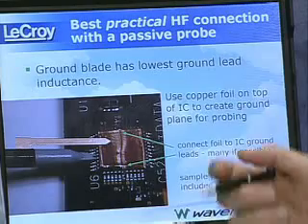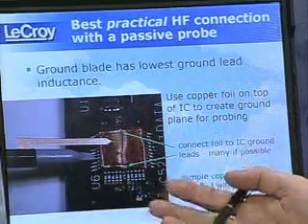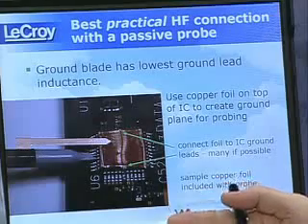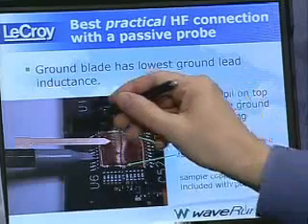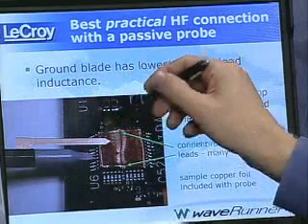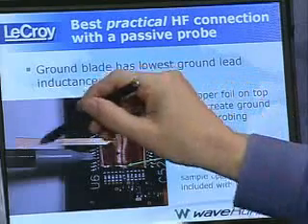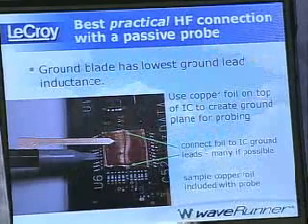Right. So people often ask what capacitance that probe is, but they often don't ask what inductance is the ground lead? And they probably should. But this blade shape of ground has much less inductance in this geometry than your usual wire shape ground lead. So it's a nice probe.